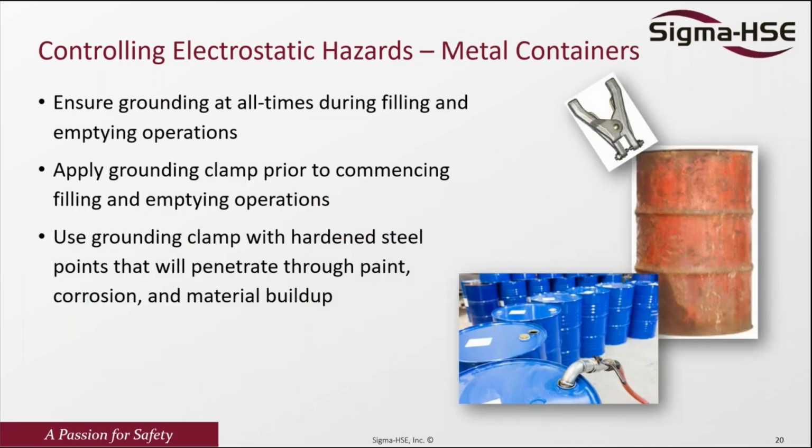What about controlling metal containers? Metal containers, and that is the example I gave. Sometimes you could have this insulative coating. Sometimes you could have some kind of corrosion. Sometimes you can have some kind of material buildup. So ensure that grounding is in place at all times during filling and emptying. And that is the problem I had with the incident investigation that I did. They forgot to connect it.